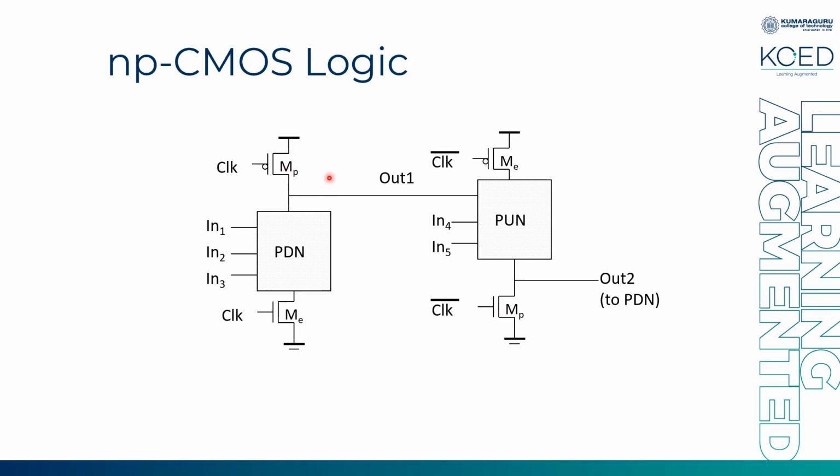So here pre-charge happens and here pre-charge happens. So here we cannot call it pre-charge; instead, we call it pre-discharge. Now clock is equal to 0, which means clock bar is 1. So this transistor is on, and this transistor will also be on. When it is on, all the voltage at this node will drain off to the ground. Okay, so this is called pre-discharging to 0, and this is called pre-charging, this is called pre-discharging.